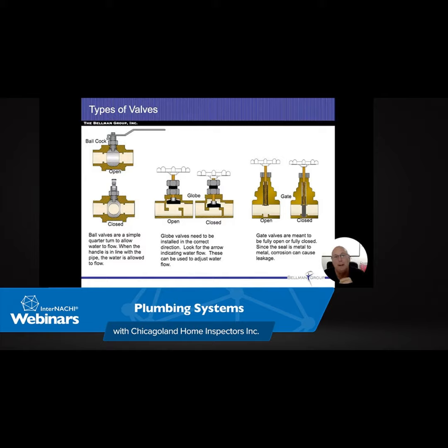Battery backups. Typically, it's going to be a secondary pump. Again, in our area, because we do have a lot of basements here, I'm a big firm believer of that. But it's not just for power outages. Sometimes you're going to get a pump failure. So at least now I've got a secondary pump that's going to step up and pick it in there.